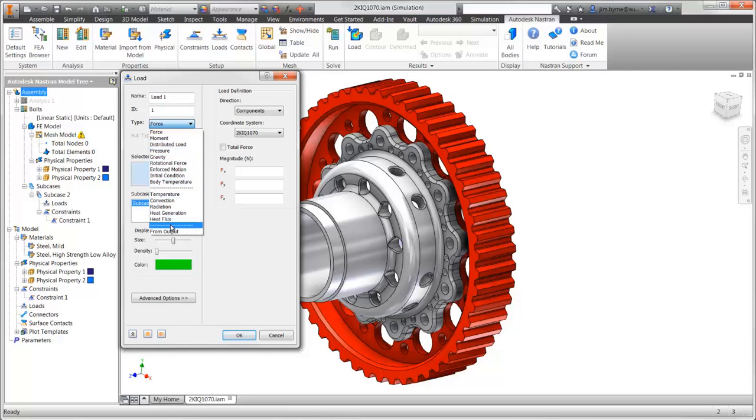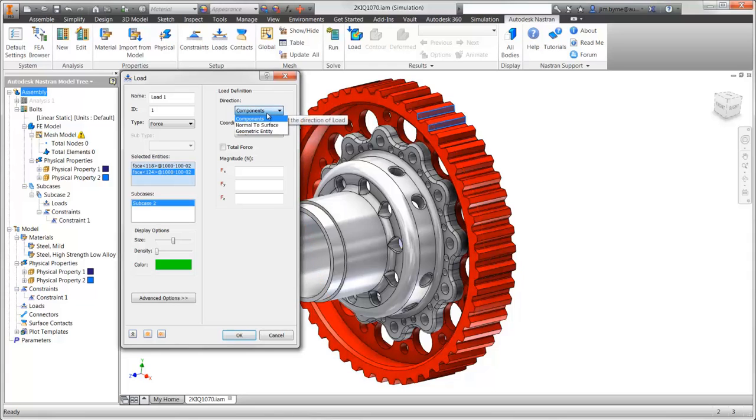Use options such as force, pressure, moment, gravity, centrifugal force, and prescribed displacement. There are also loading conditions for thermal studies such as heat power or prescribed temperatures. These loads can also be described with variable distribution for hydrostatic scenarios or bearing loads.